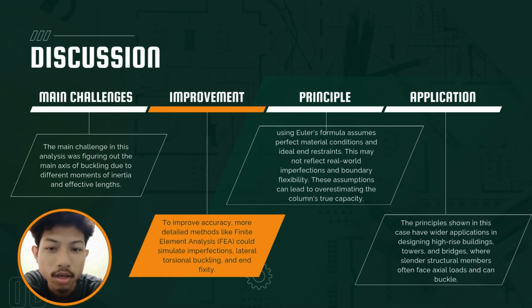From our study, the improvement that we think we can make to improve accuracy is a more detailed method like finite element analysis, FEA, which could simulate imperfections, lateral torsional buckling, and end fixity. So that's for the improvement.